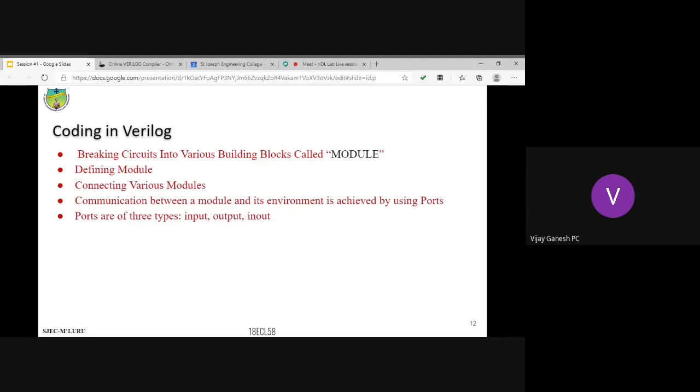Okay, there you can have multiple modules because it is a concurrent way, and the keyword for that is module. So here we are not going to use the keyword main, but instead we are going to use a module. Once you have created the modules, we just connect the different modules with wires, as we connected in the lab.